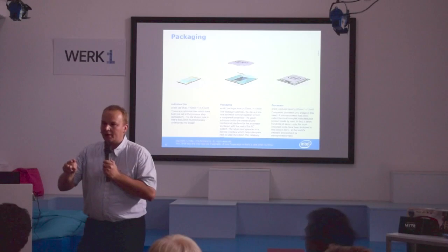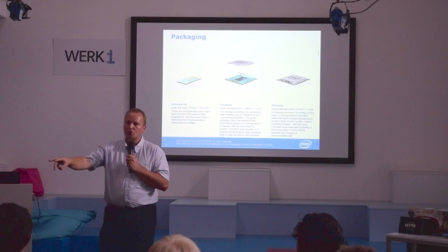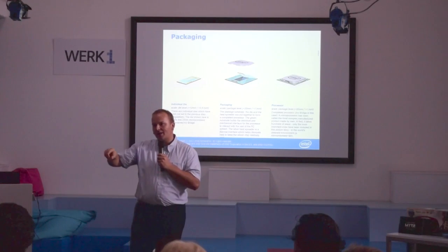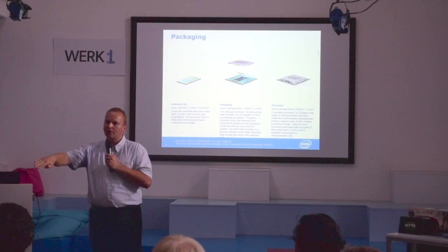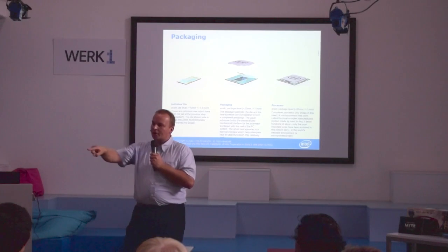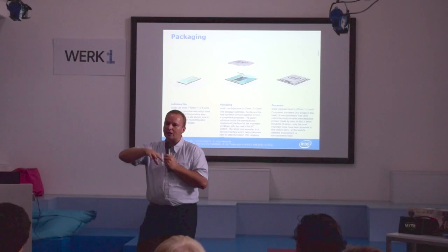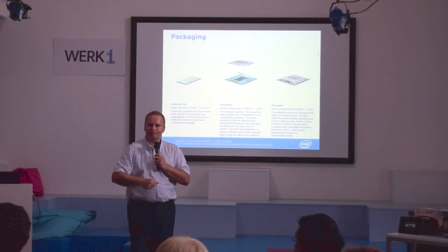How do we differentiate? That's done with a testing machine that hooks up to connectors on that wafer. The wafer that I'm showing here doesn't have balls attached to it, so it's nicer to look at. In reality, the front side actually gets ball connections on it, and then you see test points that you can use for those testing machines. That's a good question. Thank you.